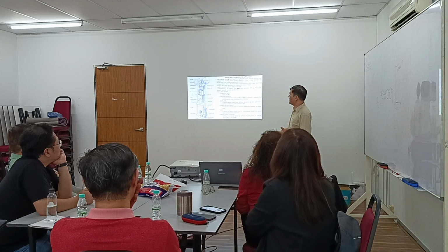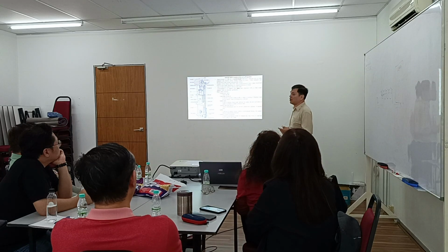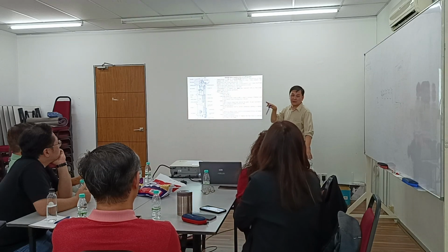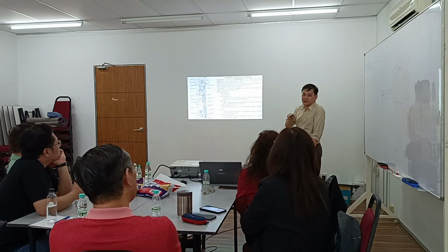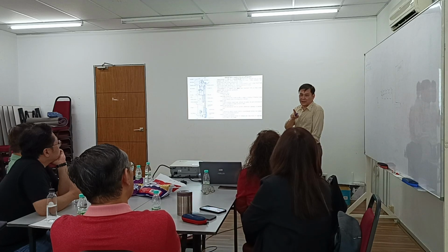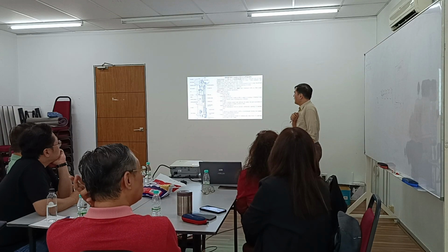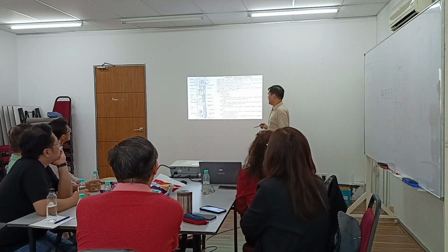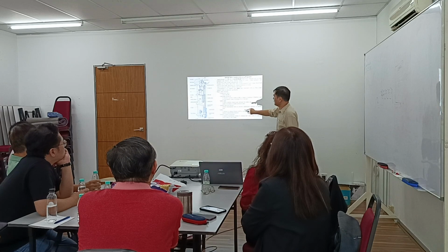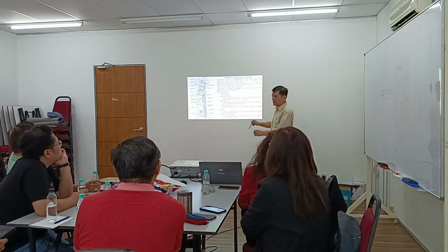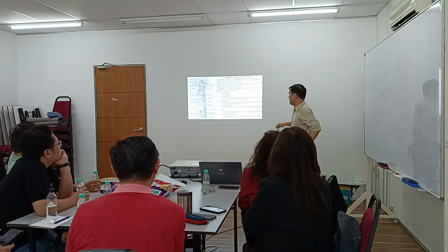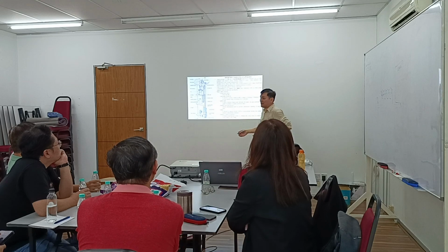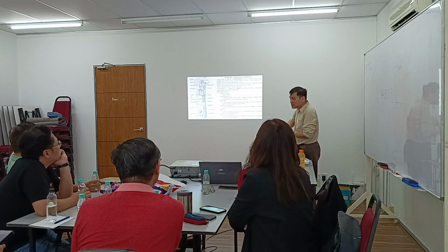So main safety device, suspension ropes, hoist the lift. This is the rope. So the law says minimum 3 ropes, and in Malaysia, the minimum diameter of a rope must be 10 mm. Okay, and then overspeed governor, this is an overspeed governor. You regulate the speed. Landing door device here, so you cannot open the landing door by force. And then buffer underneath, in the event of free fall, at least we have some buffer to absorb the energy.